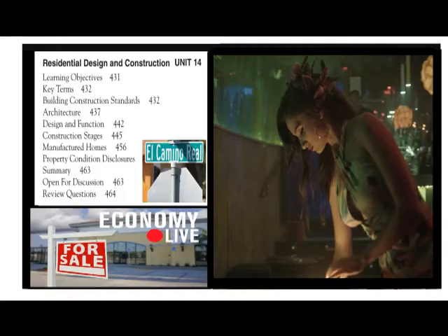The wood frame house typically rests on foundation walls of poured concrete. The site is excavated, the foundation walls are poured into wood forms, the wood forms are removed after the concrete has cured, and dirt, backfill, is moved back against the walls.